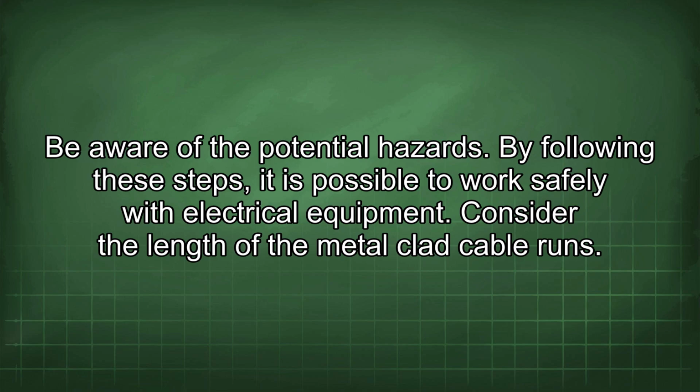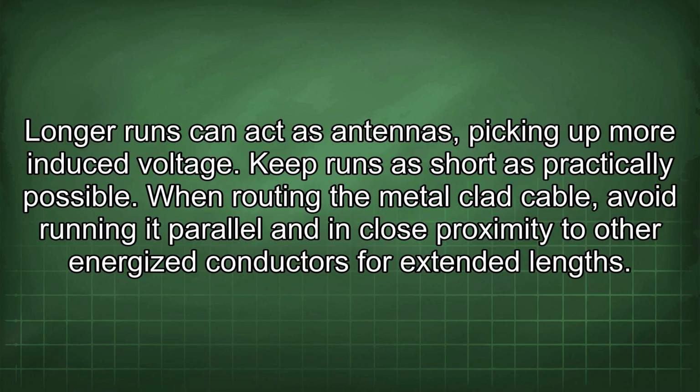Consider the length of the metal-clad cable runs. Longer runs can act as antennas, picking up more induced voltage. Keep runs as short as practically possible.